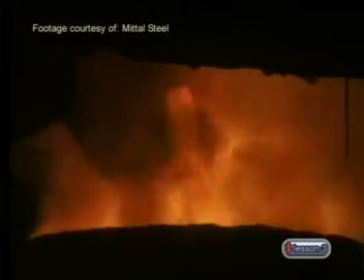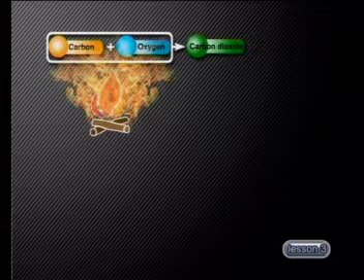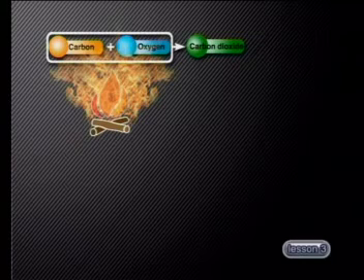What are coke and lime? Well, we're not talking about drinks. Coke is coal that has been heated until it is almost pure carbon, and lime is calcium carbonate. Now let's check on what happens inside the blast furnace. Hot air is blown into the furnace to burn the coke. The carbon is oxidized to form carbon dioxide. This is an exothermic reaction. The heat energy of this reaction pushes up the temperature to over 1000 degrees Celsius.